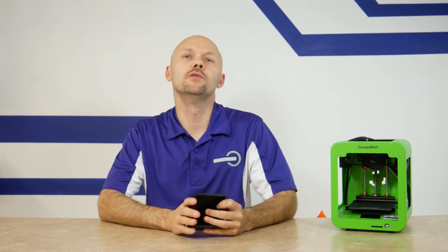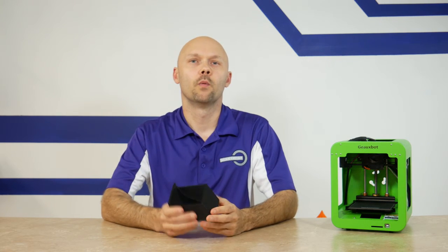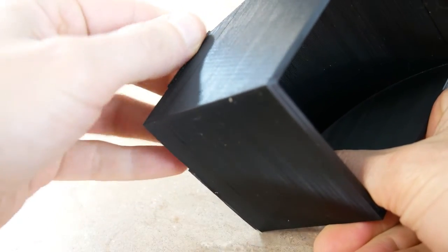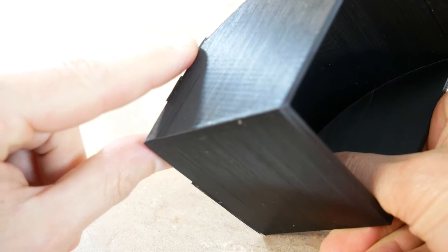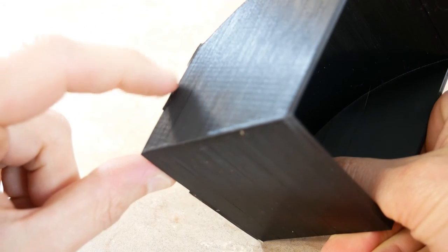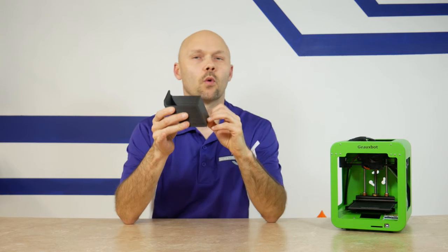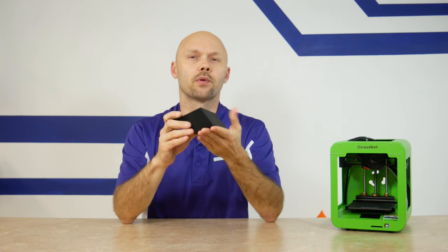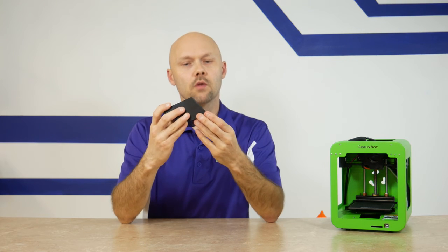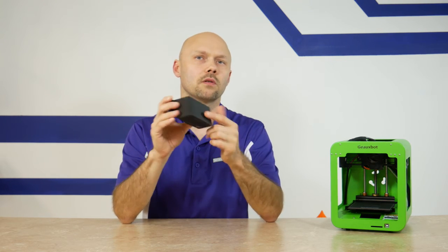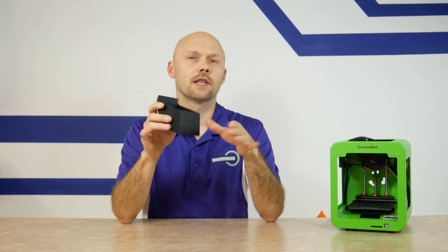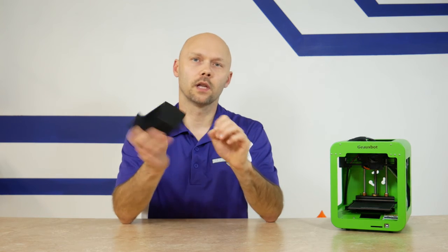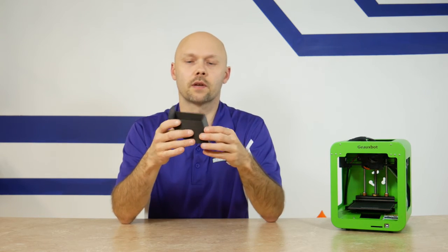Another setting you may use from time to time is the brim setting. When you turn on the brim setting, what happens is the 3D printer prints an edge around the base of the perimeter of the print. This is used to help the edges from the bottom from curling up. It also helps from warping, and it's really good for sticking to the bed a little bit more. Now this 3D print that we designed was okay, but we noticed from time to time one of the edges may curl and would really deform our prints. So engaging that brim layer helped to have this extra layer around the outside, which you peel off at the end. And if it gets messed up during printing, it's okay.